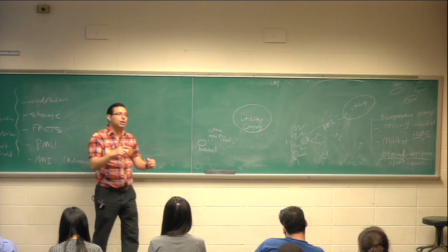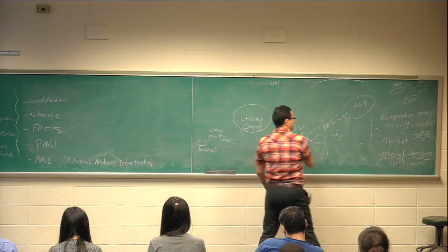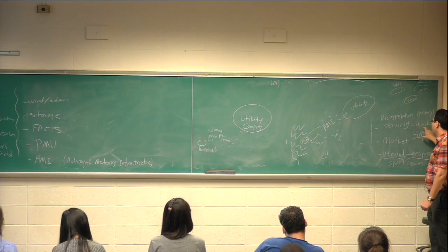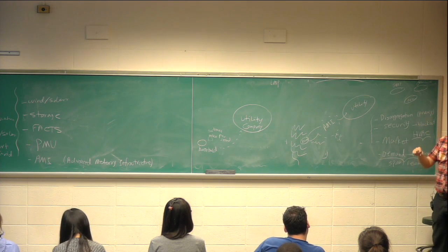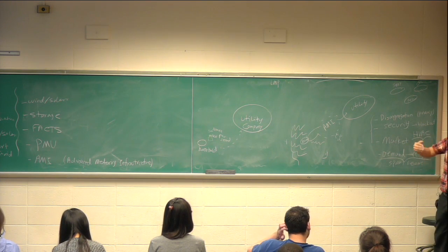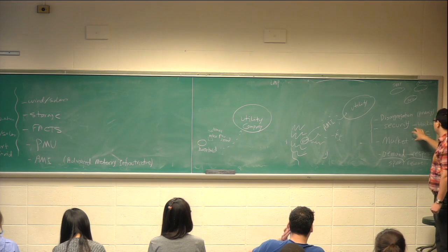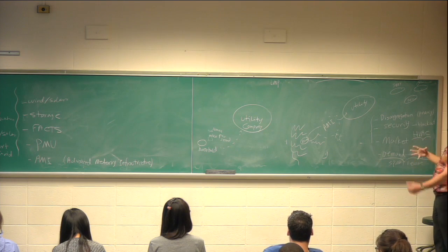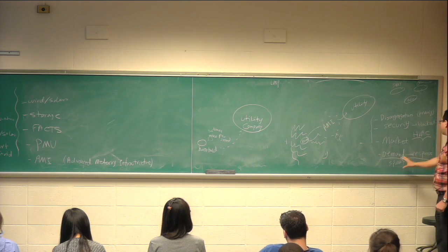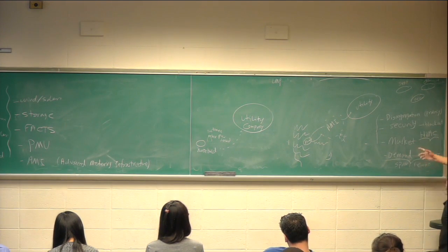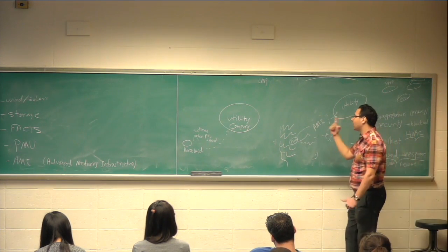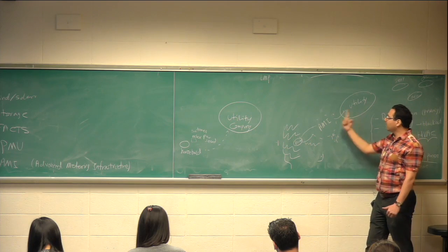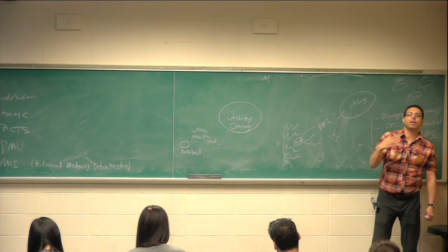So maybe the utility company can deal with this by controlling devices which are not very important. They're not critical in terms of using power right away. It could be HVAC, it could be a fridge, it could be types of devices for industrial loads. It's even better. And that's the notion of demand response. Demand response means you potentially adjust your demand in response to the price that you get. You can do it in real time, or you can do it based on a contract.